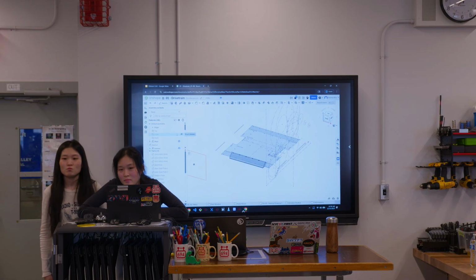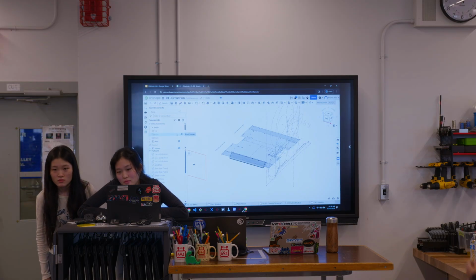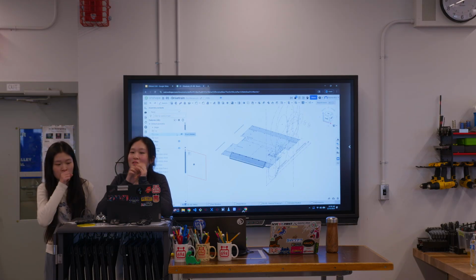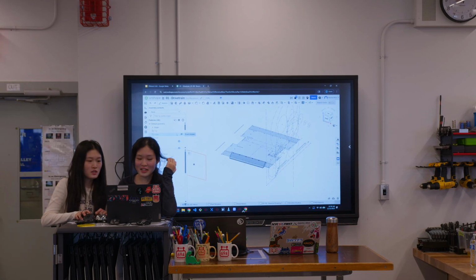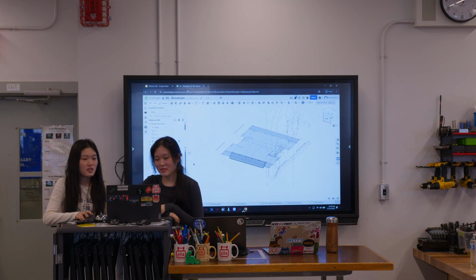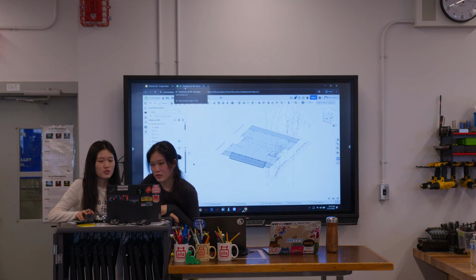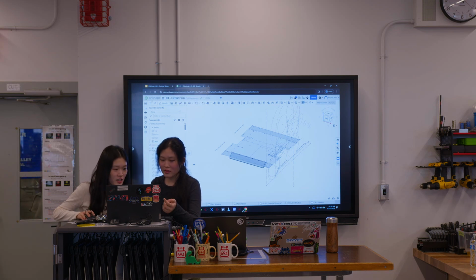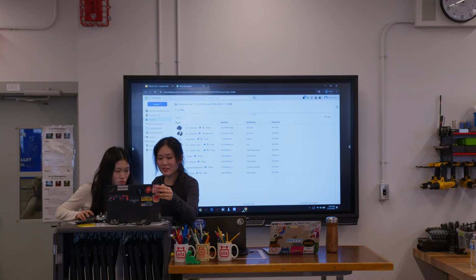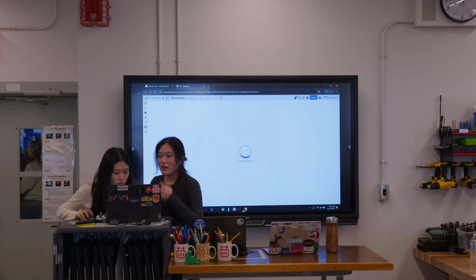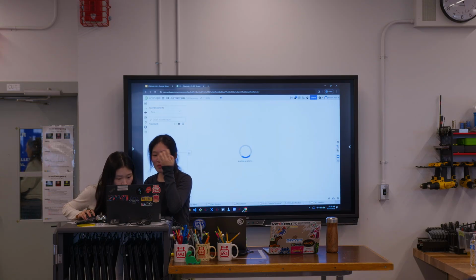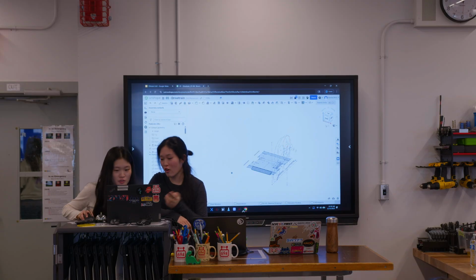Would you have any suggestions for how to pocket things, or just a general sense of how to pocket things efficiently? Yes. There are actually two ways we do it. One is to just use the FeatureScript Lighten, which is very popular. It's right over here. Okay, so first, Lighten is the most popular tool. It's kind of nice. You just draw lines.